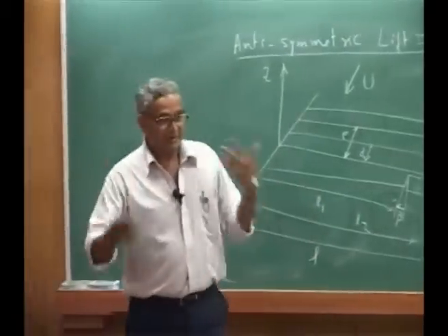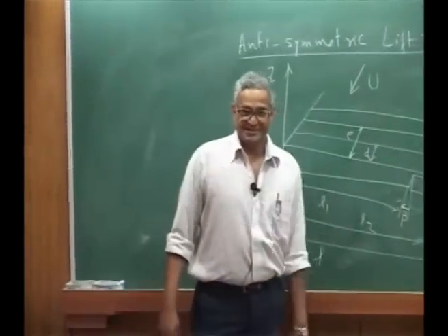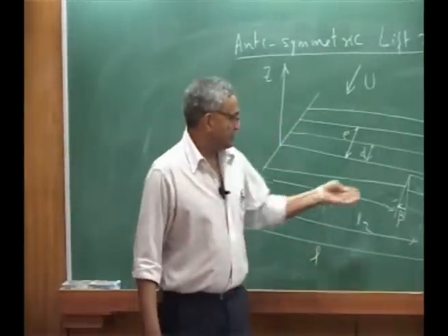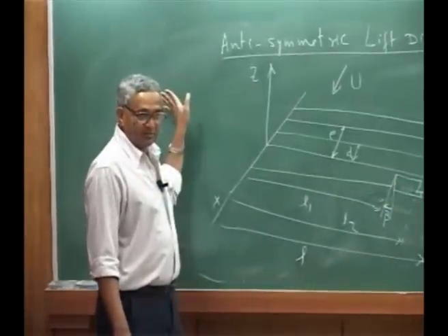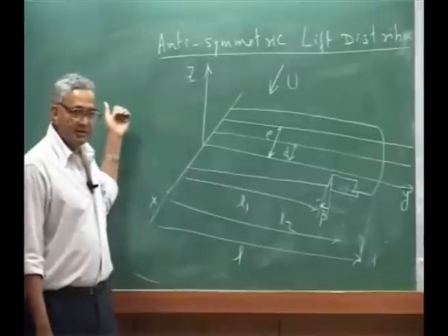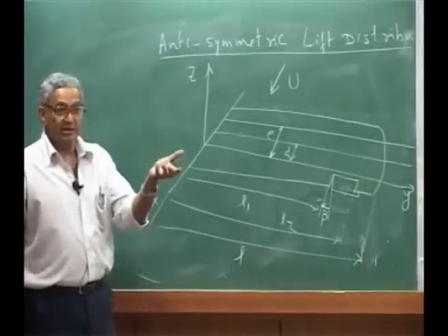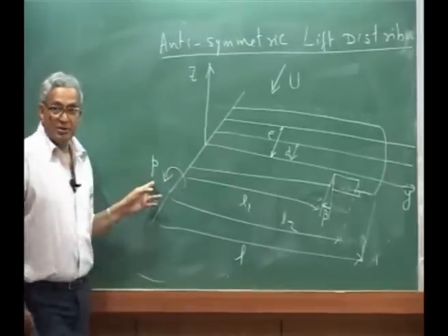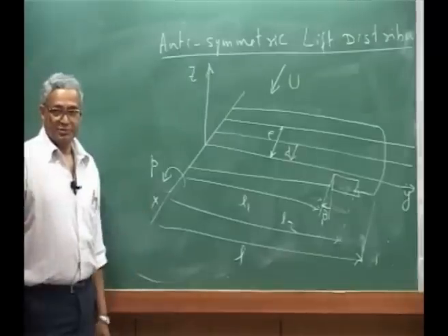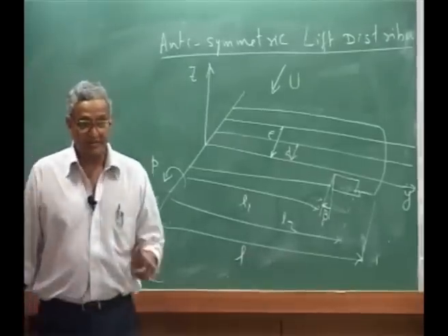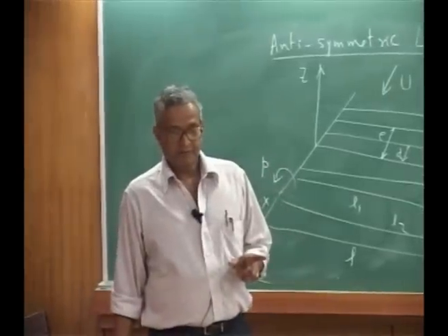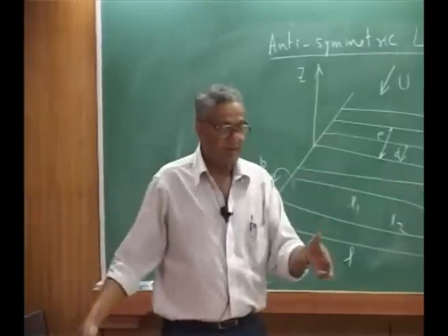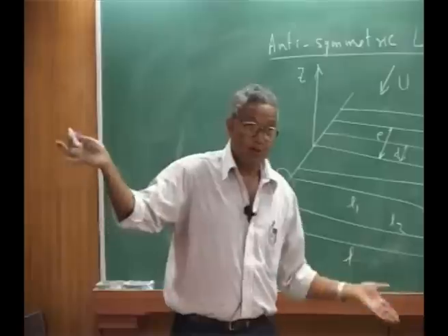Next is because I am changing my lift, so I can generate a twist also. So that is a secondary effect. And on top of it, because you have deflected, the other side also will deflect up. So one side load is increasing, another side load is decreasing, so the aircraft will start rolling. So the rolling will be, this is the roll rate I am taking. Okay? Because initially you will get a roll acceleration, please understand. Because when you deflect, initially it is flying. What happens? You change lift on both sides, there is a roll acceleration will come.